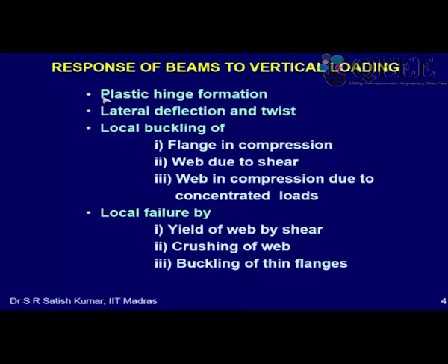We have just seen that any point reaching yield stress is not going to make the beam fail, because steel beams are ductile. So they have the ability to yield when the stress reaches yield point. It is only when the plastic hinge forms and a mechanism forms that the beam will collapse by plastic mechanism. There could be beams which, when loaded vertically, will buckle laterally, similar to a column. When you apply a load, they buckle and fail.